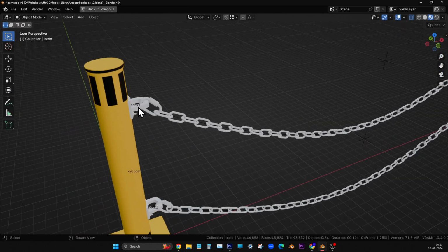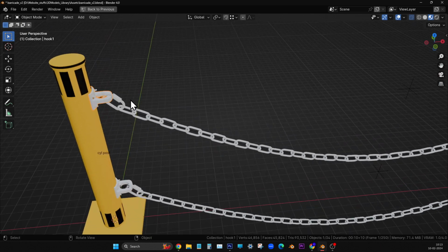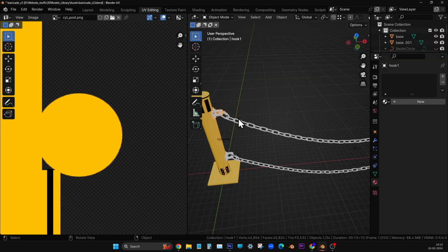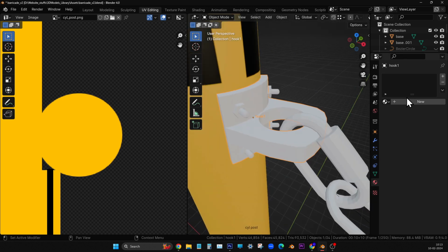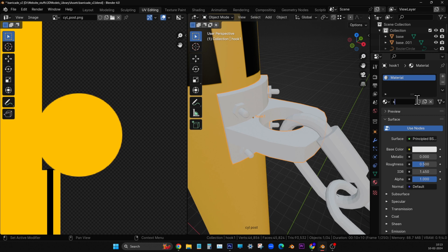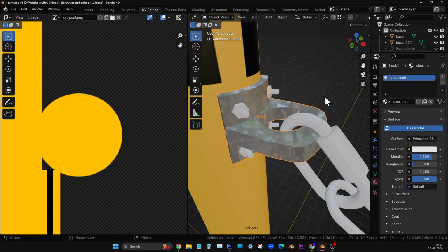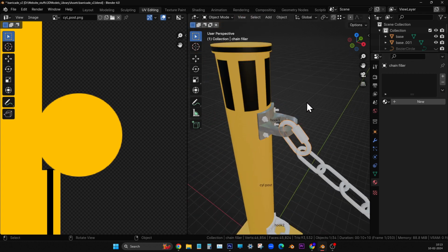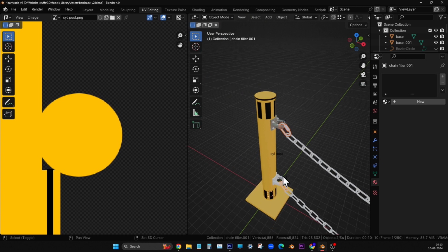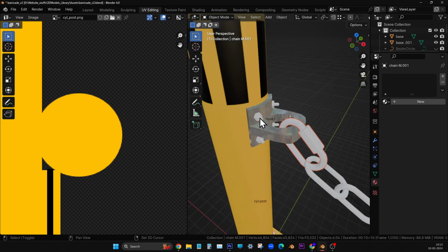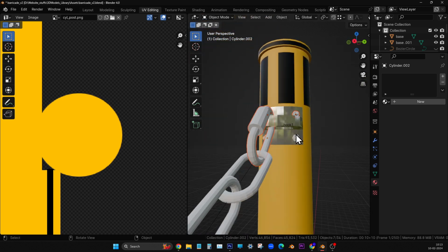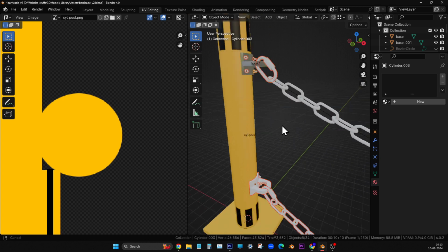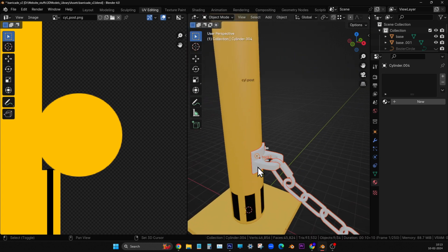So I'm doing the same thing you did. For this one, we need steel texture. Go there, zoom in, and then apply the steel material. Sorry, and then roughness 0.05 with metallic 0.8. Now we just have to select all the objects. I don't know whether in your case you selected these nuts and bolts or not. So, right.